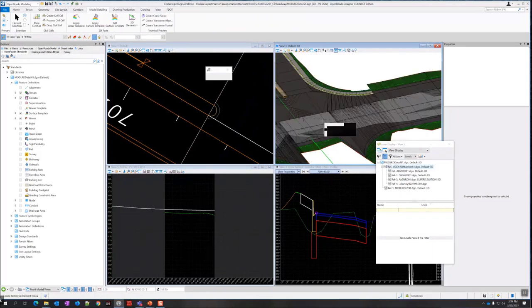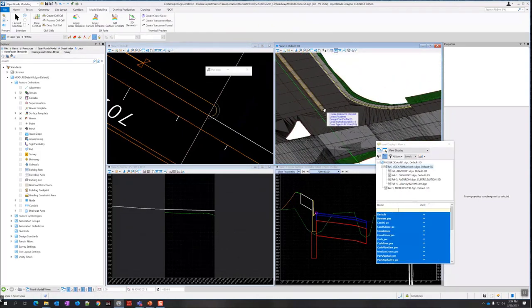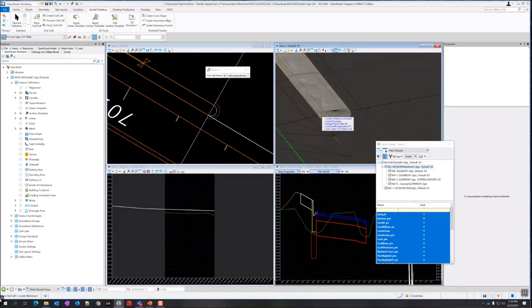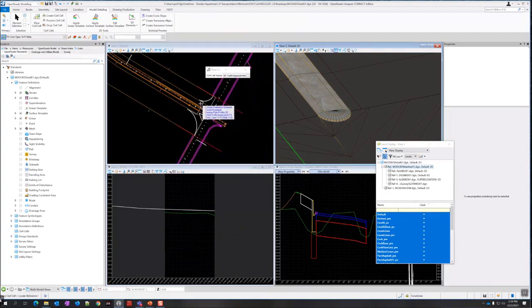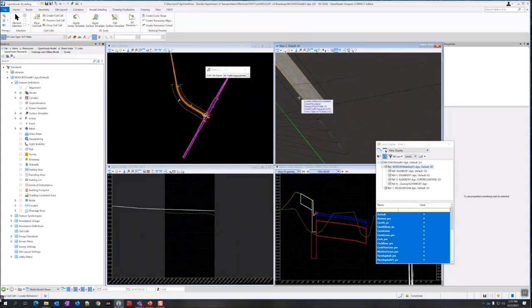Display. So you can see it lines up pretty well. Looks good. Now, if you want to get really fancy, we didn't clip the pavement underneath there. If you wanted to get really fancy when we built this line, you could have traced the nose and cut that out rather than just doing straight across. If you want to be more precise, because technically you probably don't have pavement under here. That's just a little bit more effort, but it certainly could have been done. Put an arc in the middle of that and snap to this point instead of going straight across like we did. So I'm going to go ahead and put the nose in on the other side.